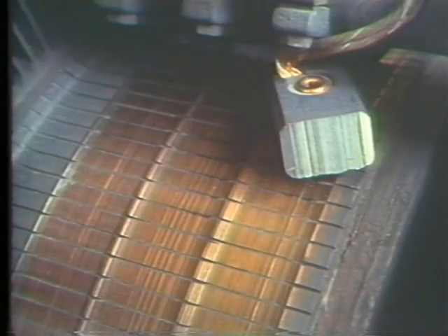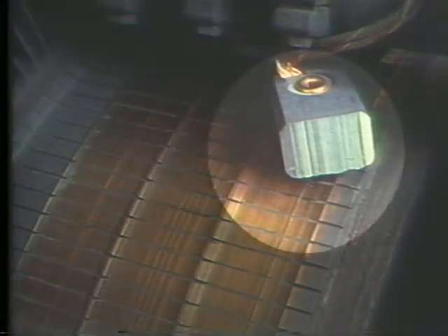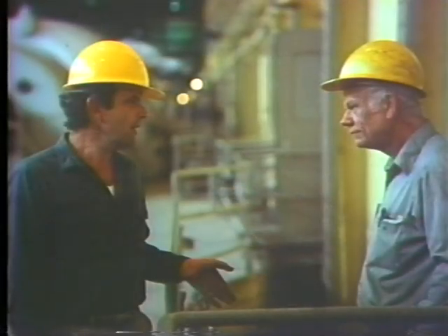And by the way, those are general rules for staggering, but it's not always necessary to stagger the rigging on every motor. For instance, you don't stagger the brushes on a 2-pole motor. And if the commutator that the brushes are riding against shows signs of wear, like this, then you wouldn't want to stagger these brushes. You can see why. The brushes and the commutator have formed wear patterns. If you move the brushes, they won't make full contact with the commutator. Instead, you should inform the foreman that both the brushes and the commutator are going to need attention.